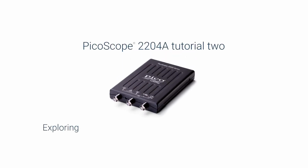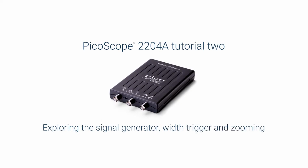Welcome to part 2 of the PicoScope 2204A tutorial. In part 1 we set up a 1 kHz square wave using the signal generator and used it to compensate a ×10 probe. In part 2 we explore the signal generator further and use the arbitrary waveform generator, or AWG, to create a glitch and then set up a trigger condition to isolate it.